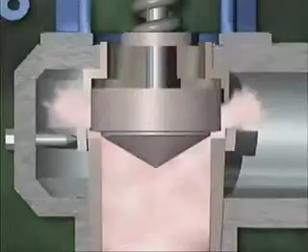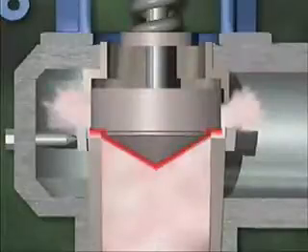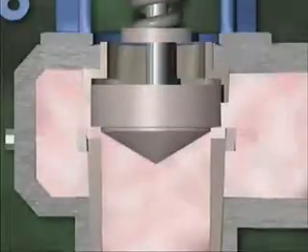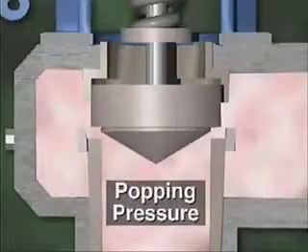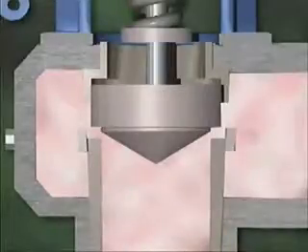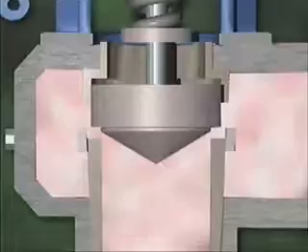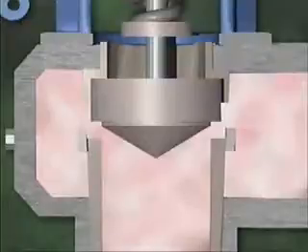Simmering lasts for only a fraction of a second until system pressure acts on the lip of the disc. As the disc lifts, the lip of the disc is suddenly exposed to system pressure. Since a larger area of the disc is now exposed to the pressure in the system, more force is being exerted on the bottom of the disc. This increased force overcomes the spring tension and causes the disc to pop open to about a 60% open position. When the valve's popping pressure is reached, the valve should open with a clean and sudden pop. If the pressure in the system continues to increase, the velocity of the escaping fluid will also increase, causing the disc to gradually lift higher until it reaches the fully open position.